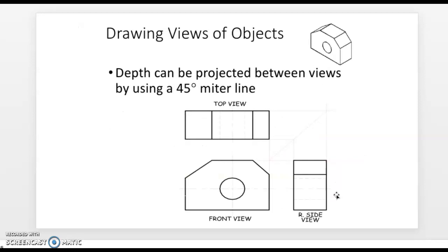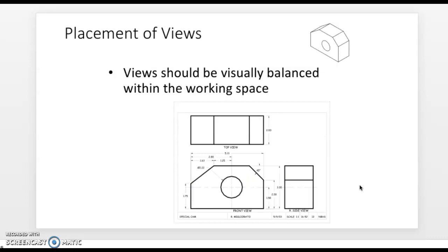As we start to wrap this up, when we draw out these parts and pieces, we have to transfer our sizes correctly. This way of drawing using a mitered line will be shown at a later time. Yet this typically shows, with the use of construction lines, how your drawings will get laid out. In closing, we need to have our views nice and neat on our template A, as you see here.